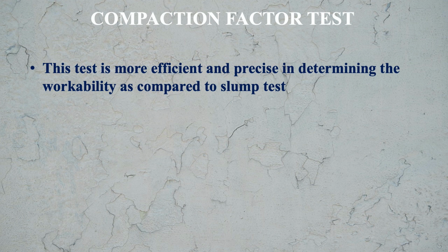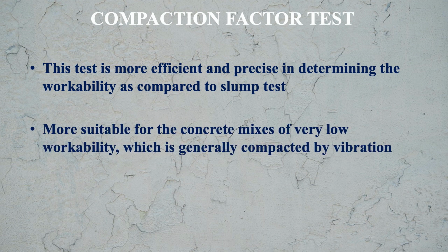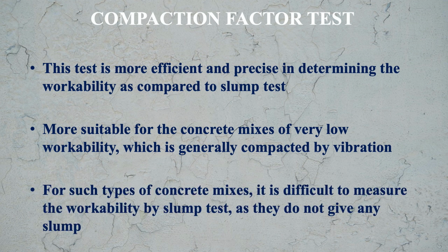Now let us see another test for workability, which is the compaction factor test. This test is more efficient and precise in determining the workability as compared to the slump test. It is more suitable for concrete mixes of very low workability, which are generally compacted by vibration. For such types of concrete mixes, it is difficult to measure the workability by slump test, as they do not give any slump. So in these cases, this test is very important.